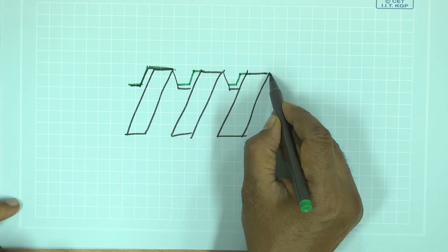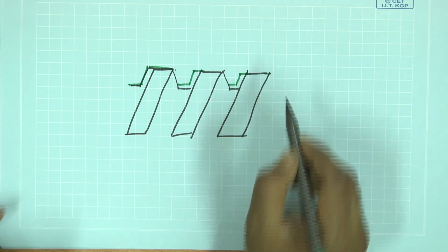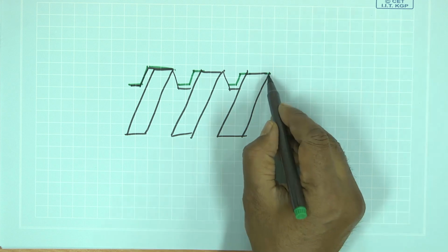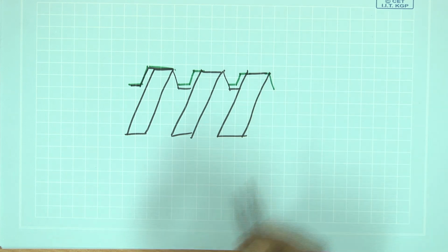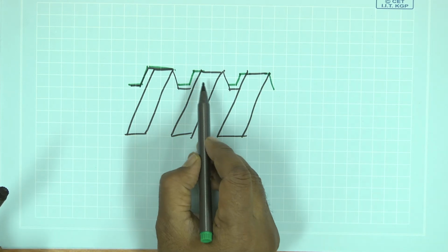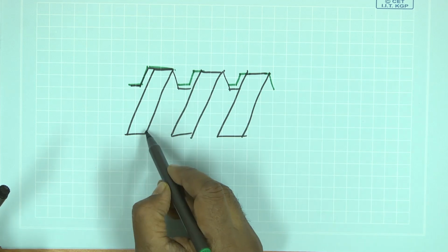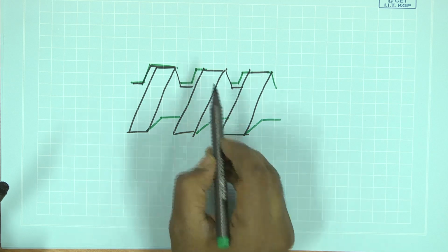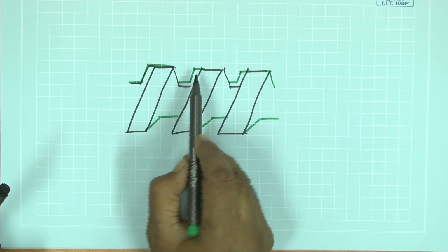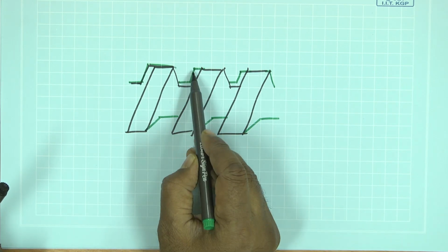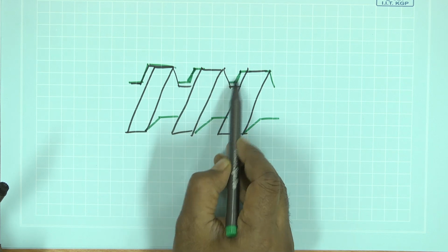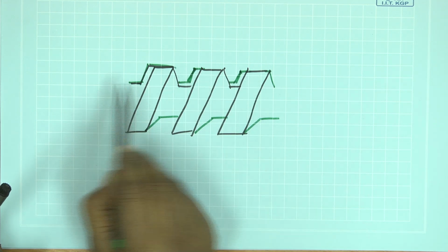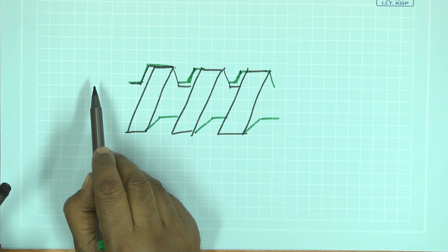My answer to this is, suppose you have an ideal case in which there is no clearance to start with, but due to wear and tear at least you will have some clearance. Whenever the screw reverses, it first has to rotate and ultimately get in touch with these surfaces, then only it can start pushing the nut in the other direction.